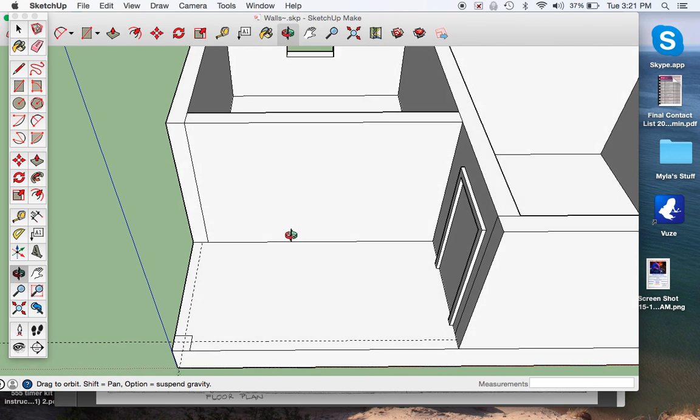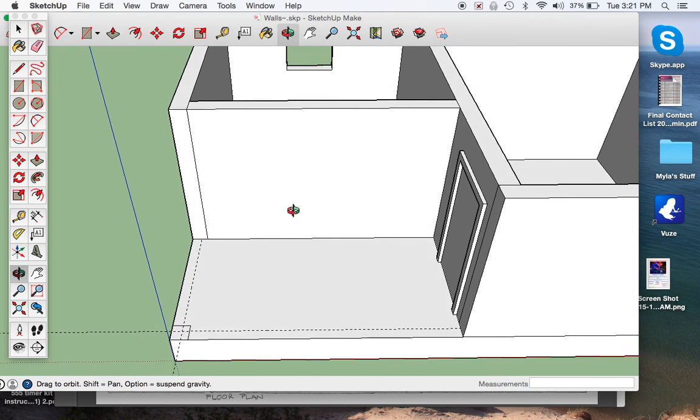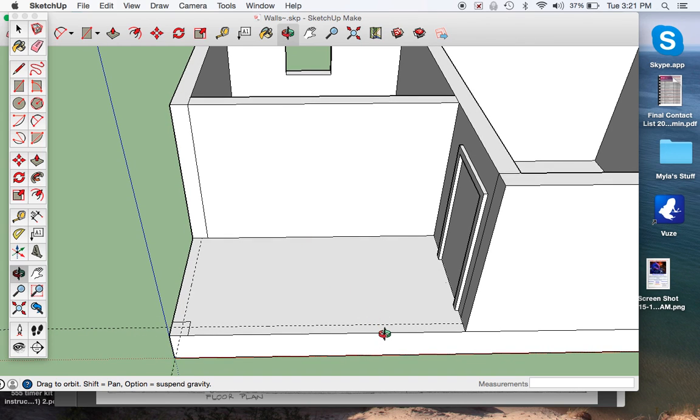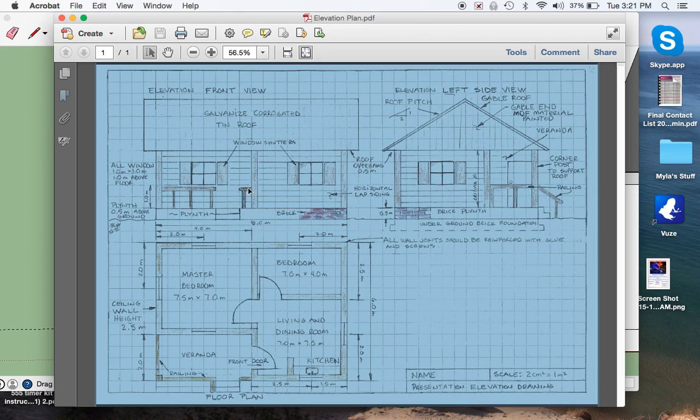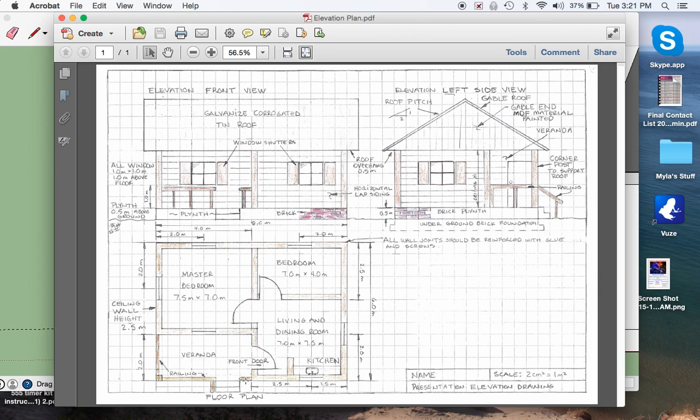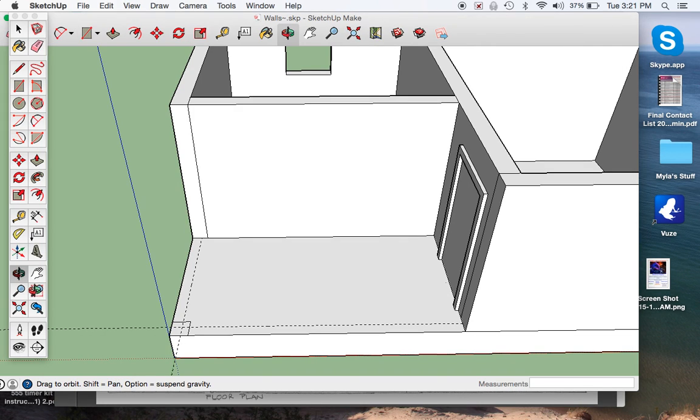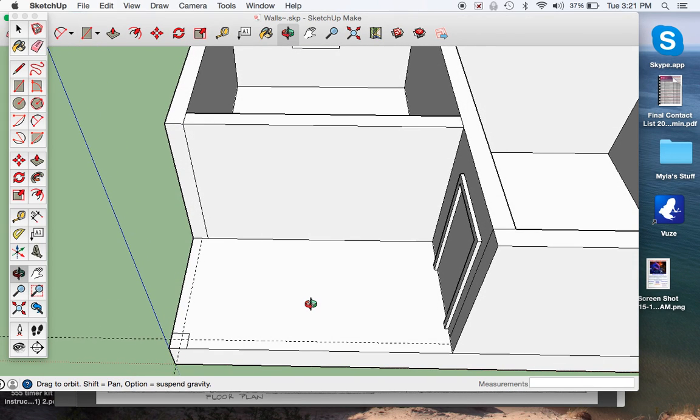Now next, what we want to do before we do the rectangle there, let's make sure we got our opening for our stairs here. Notice this gap right here. There's a little bit of a railing there coming up, as you can see over here in this part there, and also right here above that. That's half a meter, 0.5 of a meter, and then we have our stairs right there if you look at above, and then which is a meter, and then the rest is the railing. So let's just lay that out so we'll have that done in advance.